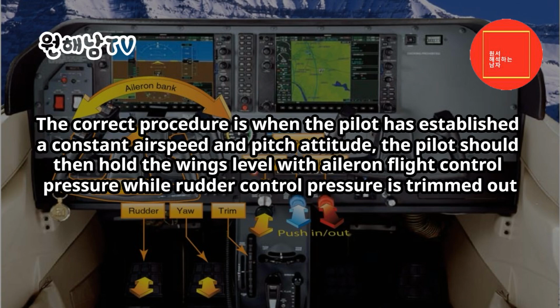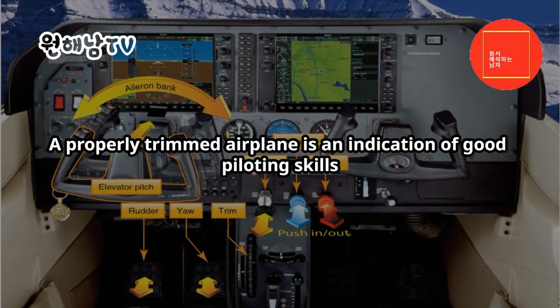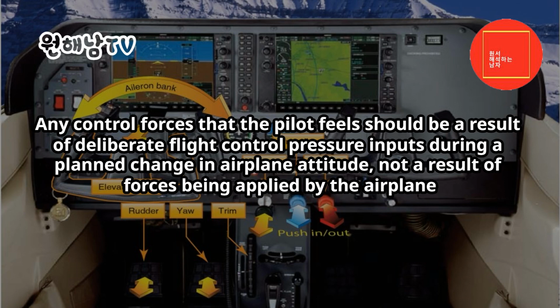The correct procedure is, when the pilot has established a constant airspeed and pitch attitude, the pilot should then hold the wings level with aileron flight control pressure, while rudder control pressure is trimmed out. Finally, aileron trim should be adjusted to relieve any aileron flight control pressure. A properly trimmed airplane is an indication of good piloting skills. Any control forces that the pilot feels should be a result of deliberate flight control pressure inputs during a planned change in airplane attitude, not a result of forces being applied by the airplane.